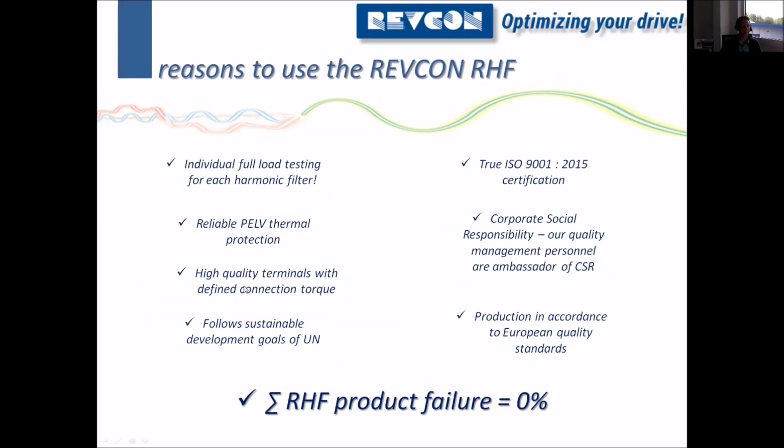If you have a big power rating, I would ask for individual full load testing, and they should have it for every harmonic filter, at least above a certain size. We do it for any size, even for the smaller ones. But especially if you have a big one, you want to be sure that it really works when you ship it around the world, and then you make a huge effort on installation, and then you don't want to see the problems that could have been detected at the factory.